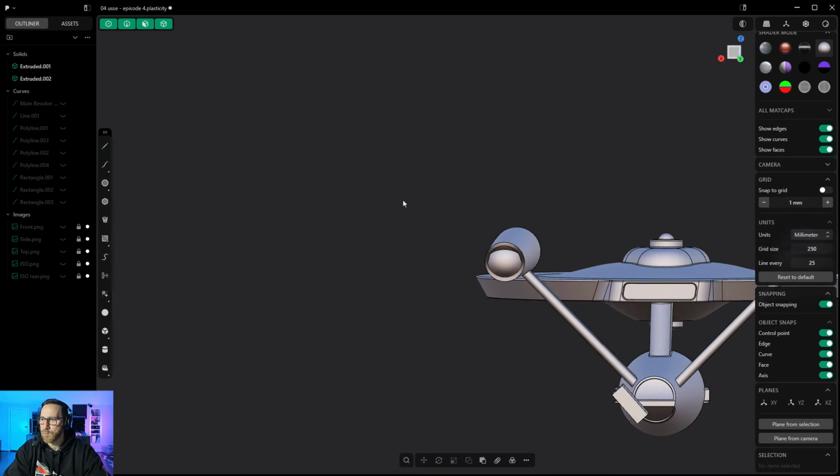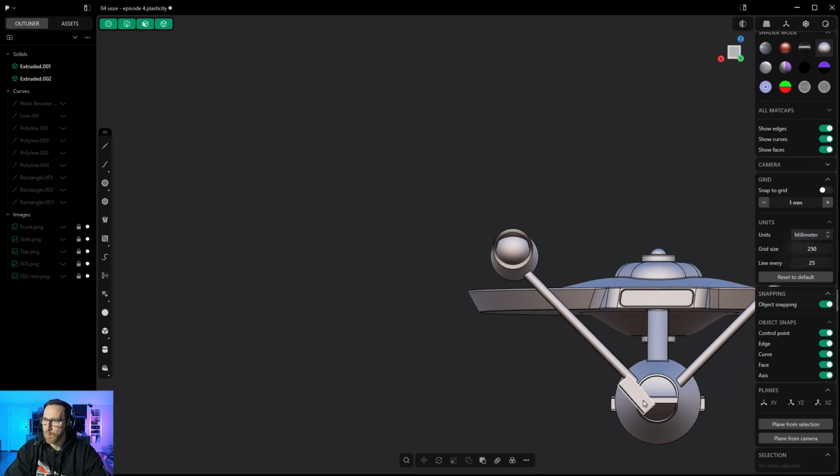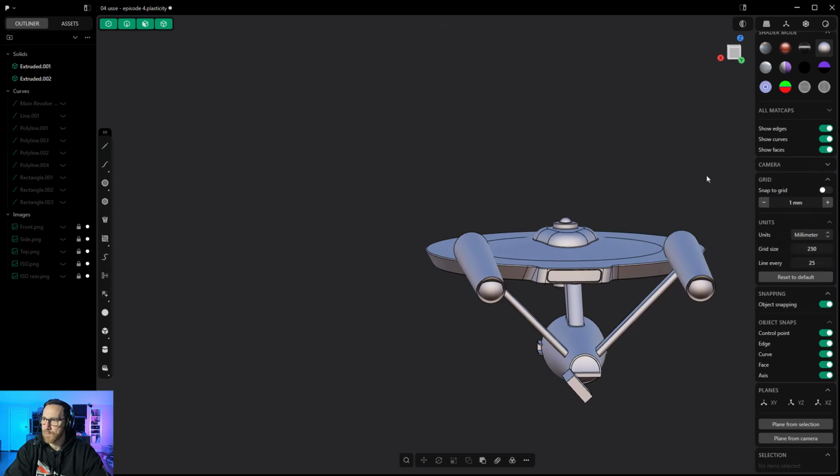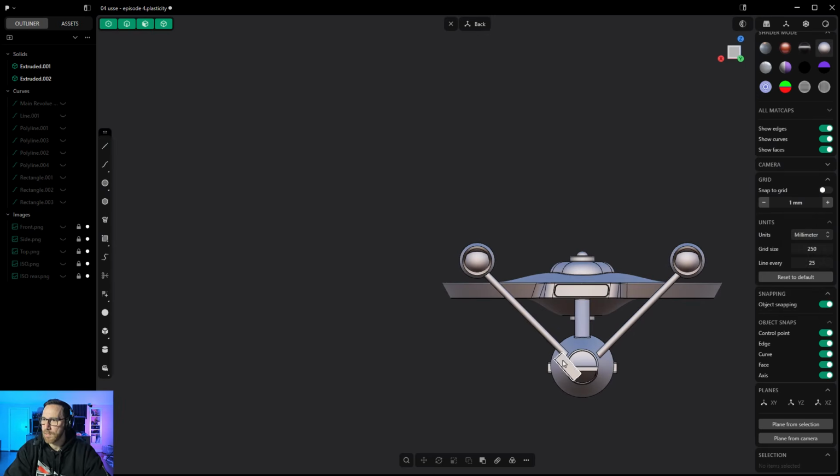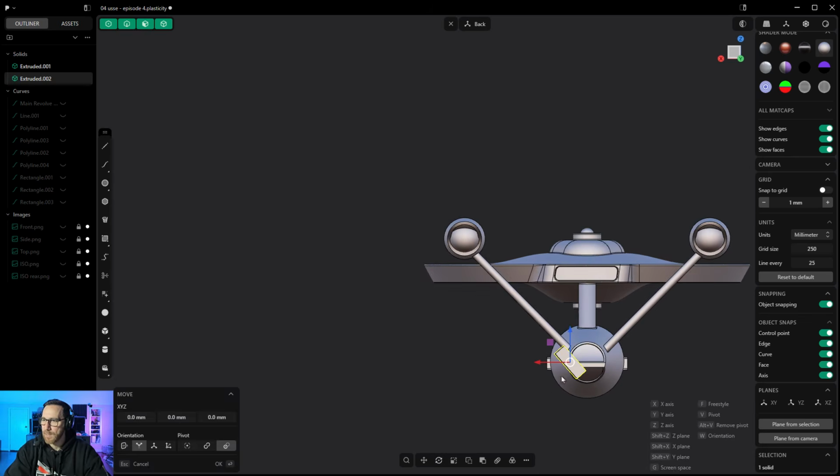And so what we did was we drew it sort of at the angle that we wanted it to be. And now to get it into its place, let's go ahead and look at it from the backside. I'm going to grab that. We're going to say move. But instead of just moving relative to the X, Y, or Z direction, what we're going to do is reset the pivot by hitting V on the keyboard. And once we do that, we're just going to select basically one of the faces here, and that'll put it normal to the direction that we created it.